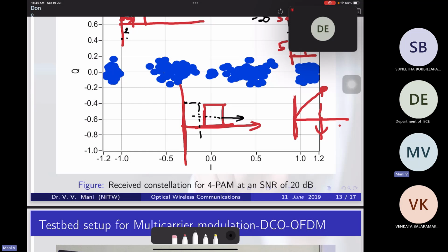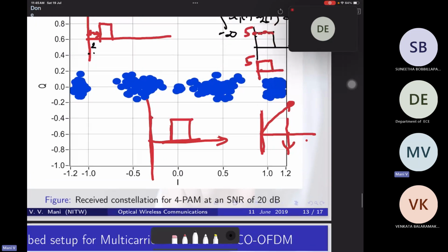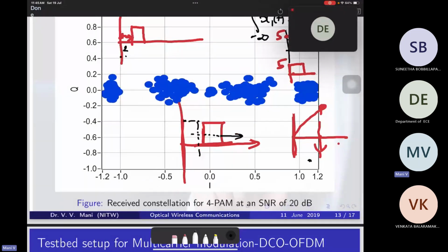You will get a maximum output when that window is exactly placed on the receiving signal, according to the principle of correlation. Where you get the maximum value is when both of them are one to one, right? So when you are moving along this direction, when it is placed right on top of it, I'll get a maximum value. That means how much movement I made, I made this amount of movement. That is my delay estimation.